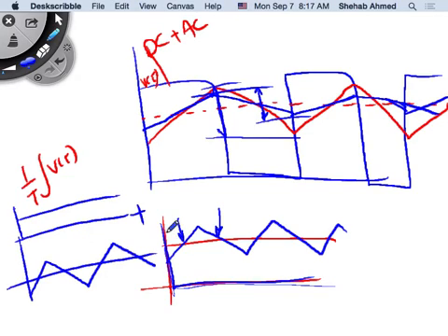Or, for example, if I gave you the Fourier series for this triangular waveform, in the Fourier series sheet that I gave you, I gave you the Fourier series expansion of this waveform. From the Fourier series expansion of the waveform, you can find the RMS value, like we did for waveforms that have multiple components. So you can find the RMS value of the signal. The RMS value for a DC value is DC.